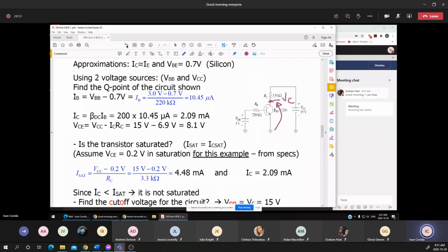The other voltage, at the base, I will label that as the VB. And we have to determine in some questions, in some examples, what is the voltage VB, or the voltage at the base of the transistor, again, with respect to ground. In this case, the VB with respect to ground is actually the 0.7 volts, which is the VBE. Again, why is it 0.7? Because the base emitter has to be in forward bias, and the VBE voltage is 0.7.